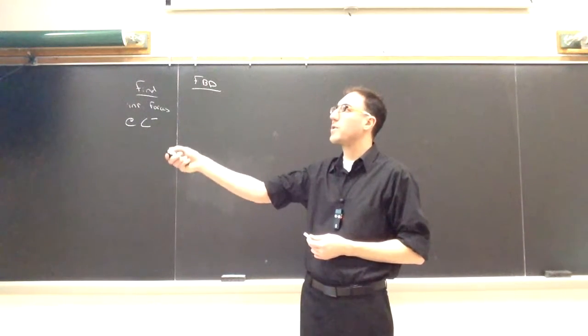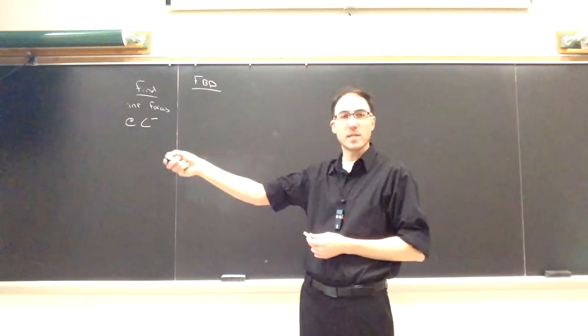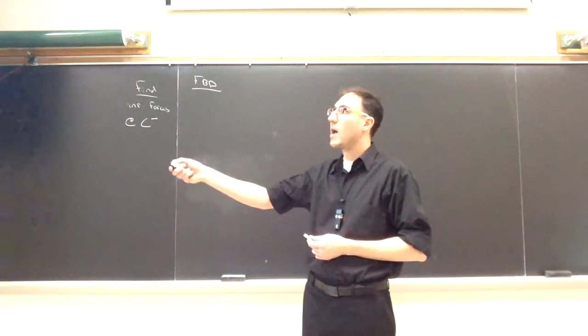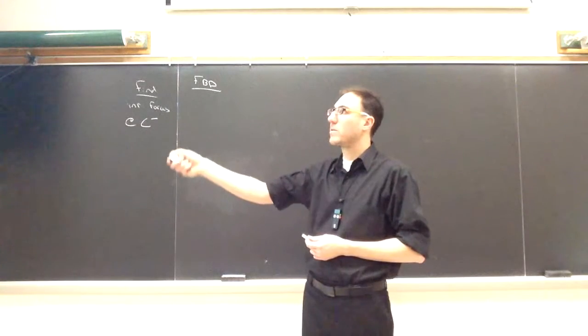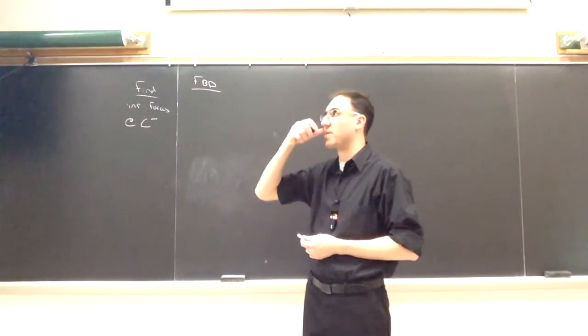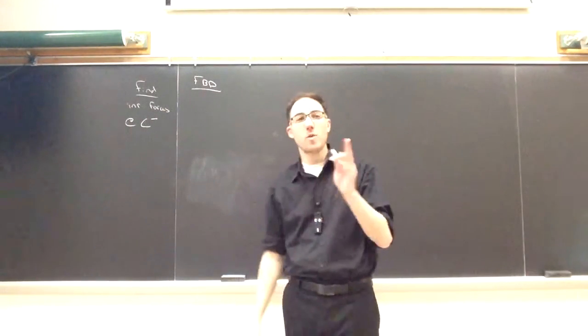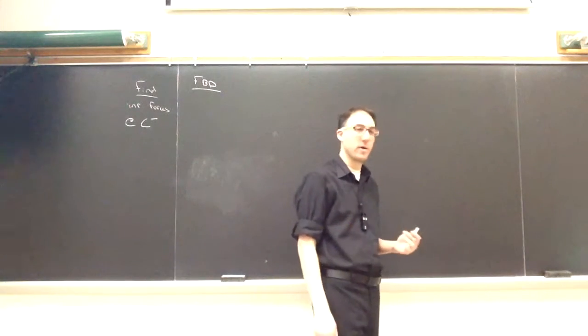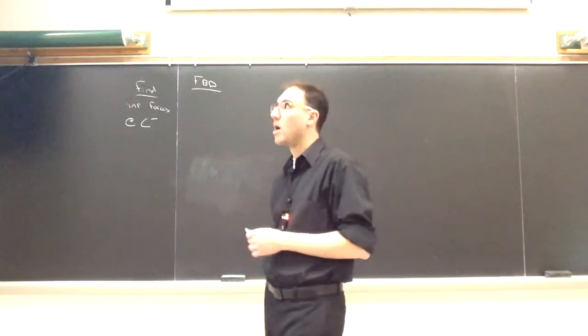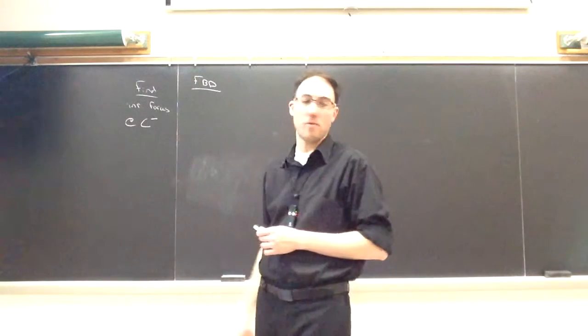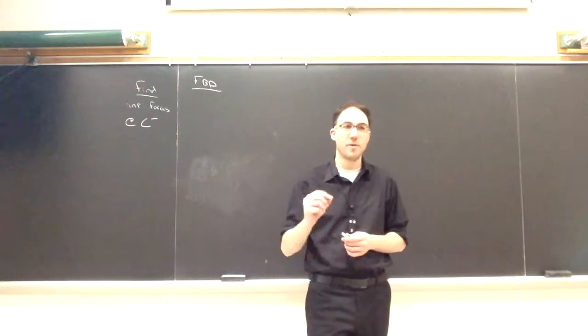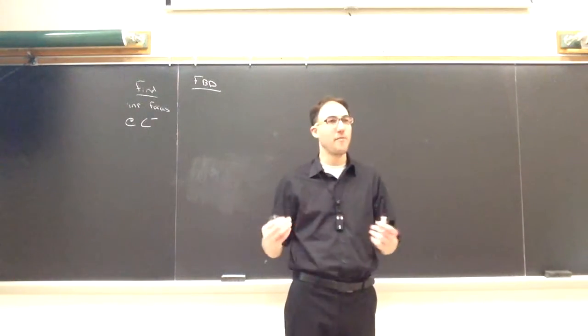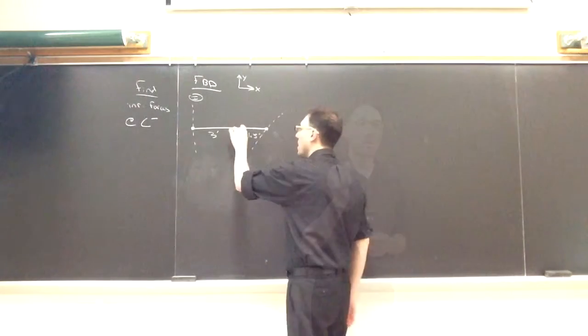But if we look at either of those pictures, everything to the left will include this collar at D. Everything to the right will have the roller, or I'm sorry, the rocker at B. So either picture we would draw for the internal structure will have an external force or a reaction force involved there. So the first step we want to do is solve those external reactions.